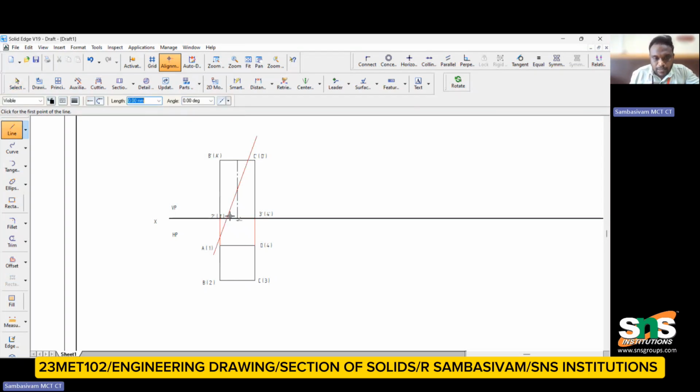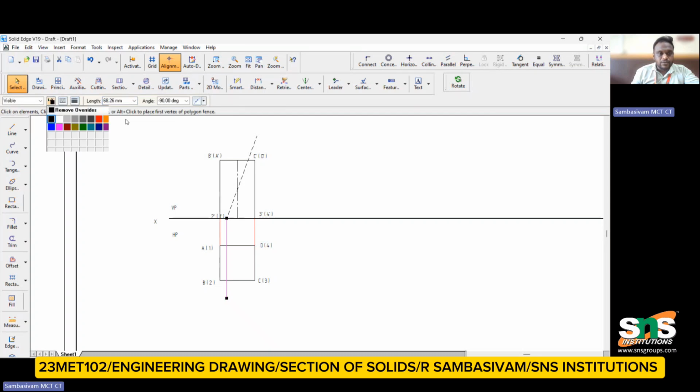Now I take this point and trim this particular portion. It touches the plane, so this is your cutting plane. I like to mention dashed lines from this point, the edge. I have to draw where it has been cutting, so I have to draw the trace lines. This trace line will be in a different color, so I am using a green-blue color for this.